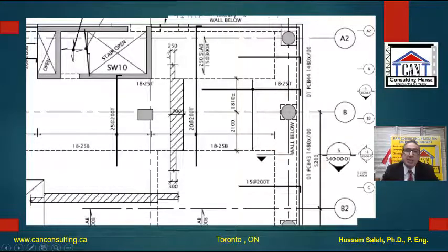And here you can see that 250 is the thickness of the slab, and you have a thicker slab, 700, and here you have another 300 from the other side. So here is shear wall number 10, and here stairs open, you have an elevator, and you have here a beam and the grid line. So that's the recess in this part.